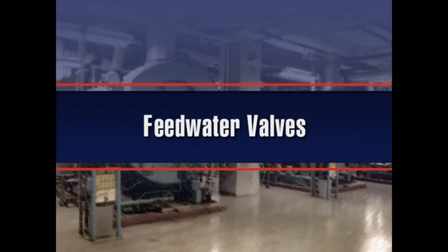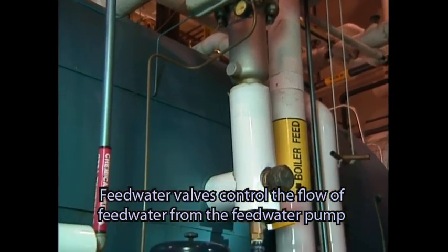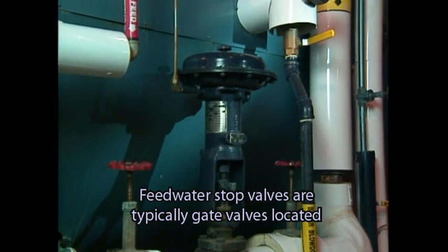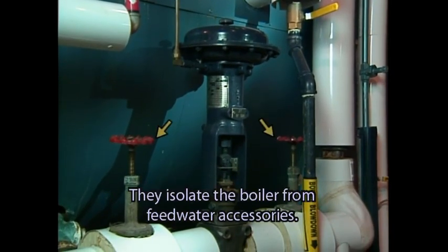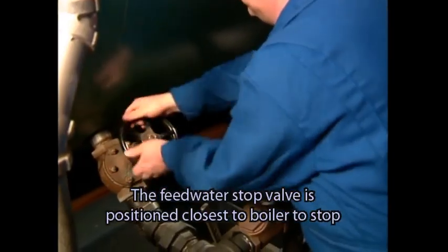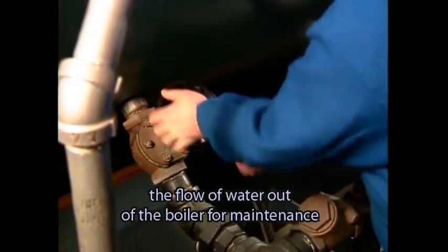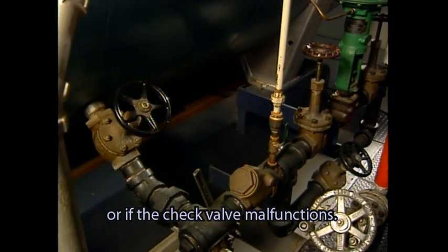Feedwater valves. Feedwater valves control the flow of feedwater from the feedwater pump to the boiler. Feedwater stop valves are typically gate valves located on the feedwater line. They isolate the boiler from feedwater accessories. The feedwater stop valve is positioned closest to the boiler to stop the flow of water out of the boiler for maintenance or if the check valve malfunctions.